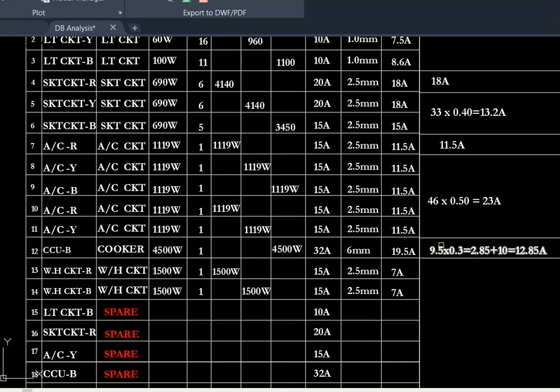Now, 30% of this is what we are going to add to the 10 amps that you've collected before. Remember that this is the total power. We subtract 10 amps and we are left with this. Now, take 30% of this leftover and add it to the 10 amps that was subtracted for the socket. It's quite simple.